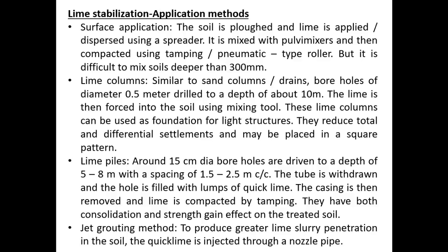Next one is lime columns. The lime columns are similar to sand columns or drains, which are widely used for reducing the settlements. The boreholes of diameter around 0.5 meter are drilled in a pattern to a depth of about 10 meter, and the lime is forced into the soil using mixing tools. The lime columns reduce the settlements and can be used as foundations for lightweight structures.